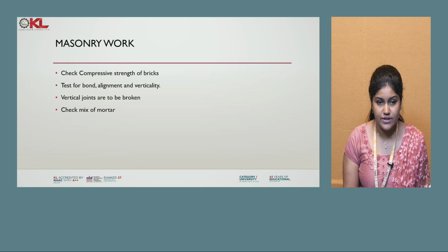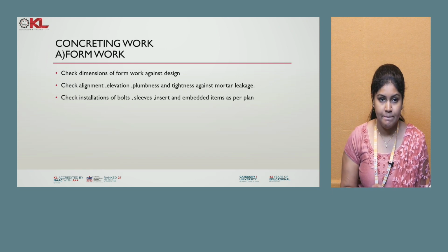How the vertical joints are broken, whether it is properly broken or any disparity is coming there. And check the mix of the mortar. After keeping all the bricks, we will keep the mortar mix and we will fix it firmly. So at that time, whether the mix is done in a proper ratio and proportion or not, everything has to be checked in the case of masonry work.